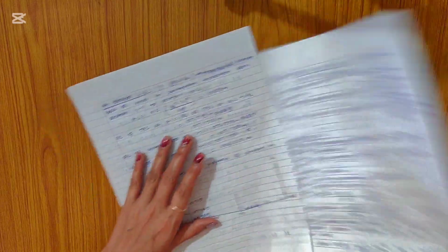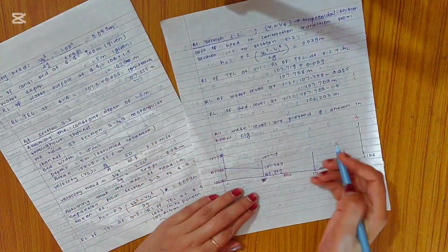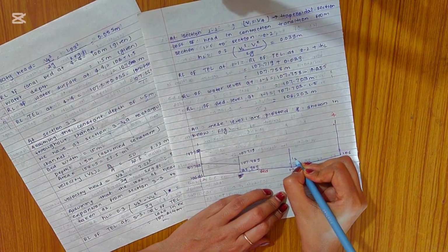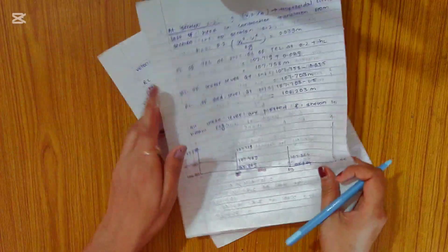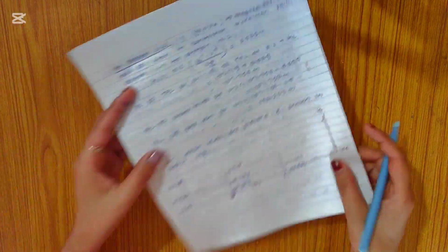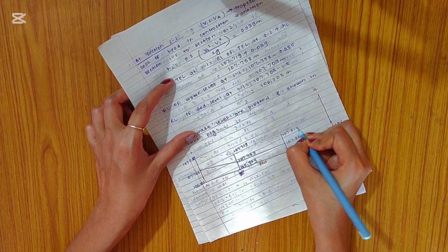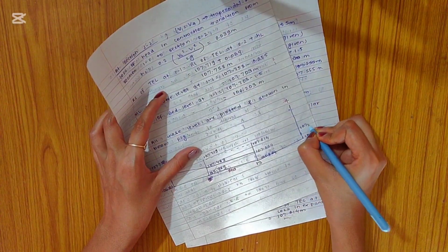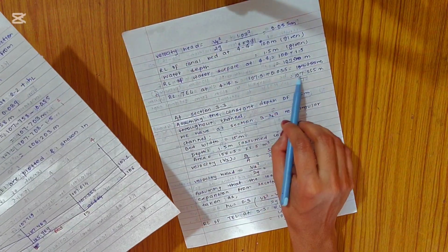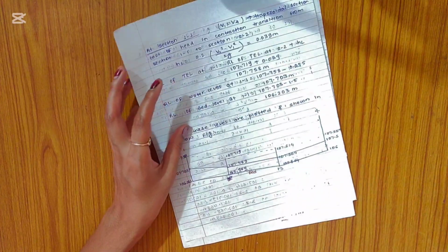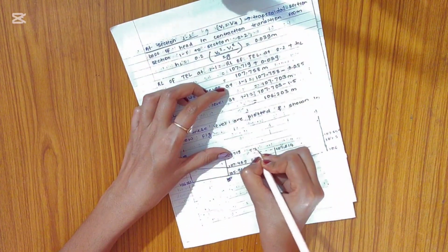For section 3, the water surface level is 107.364, and total energy level is 107.614. Now at section 4 the calculated water surface is 107.5, and total energy level is 107.555 meter. So this is plotted for the bed, this is for the full supply level, and this is for the total energy line.